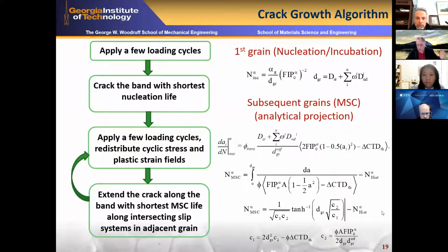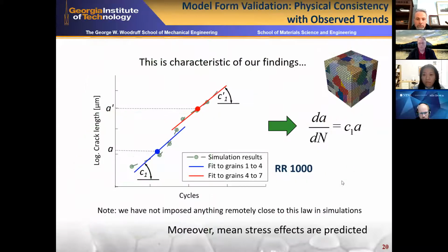And in the process, this incorporates both plasticity and roughness-induced closure, right, which are very difficult to consider in classical elastic plastic fracture mechanics calculations of small cracks.